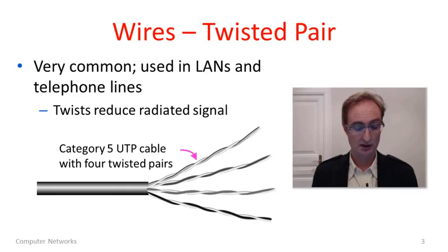This cable shown here, the category 5 UTP, stands for unshielded twisted pair. That is a common Ethernet cable. You can see in here that there are 4 pairs of twisted pairs. The twisted pairs, each one is literally 2 wires twisted around. The signal is carried as a voltage differential across those wires, and they're twisted just to help reduce the interfering RF signal that's radiated. At least they reduce the radiation of that signal, and by reducing that we reduce the interference between adjacent pairs of wire.